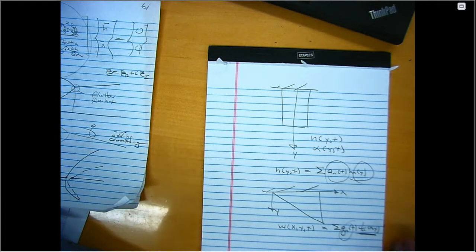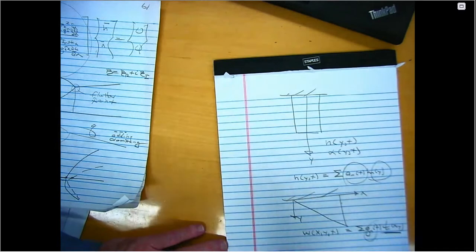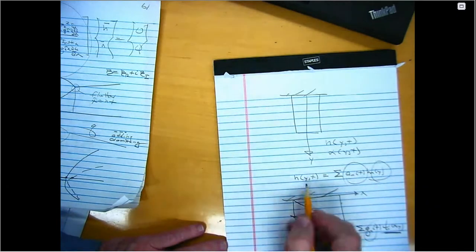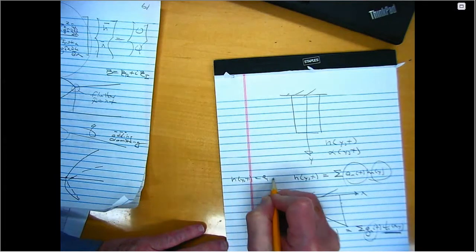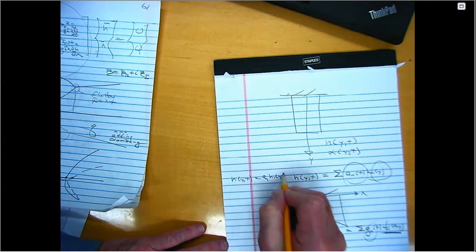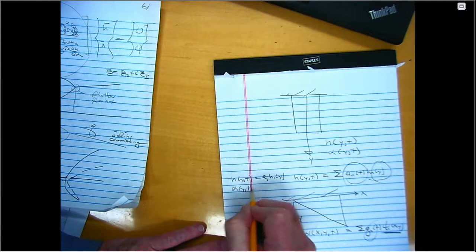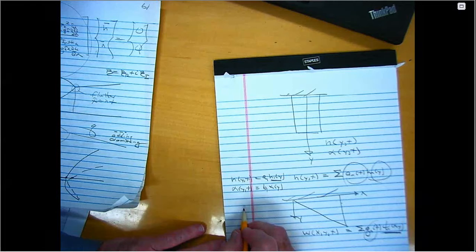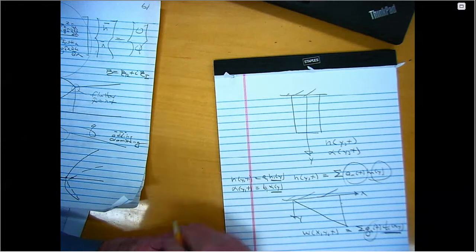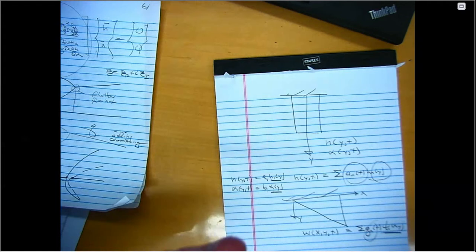So with your second degree of freedom, it would just be like a second variable with the deflection. Well, if I want just a two degree of freedom flutter model, in this case I would just use one term for h, and I'd use one term for alpha, b sub 1, alpha 1 of 1, right? Where this would be the first bending mode of my beam rod, and this would be the first torsion mode of my beam rod. And I would end up with a form of equations that's identical to what we just discussed.